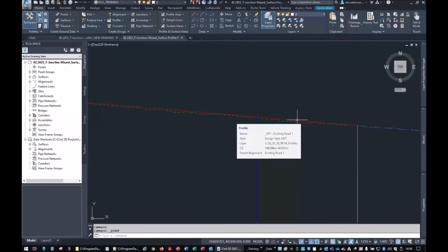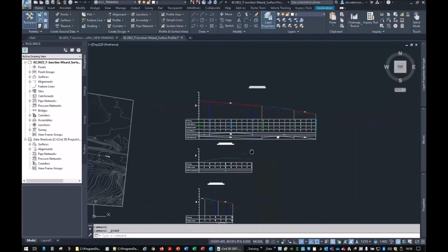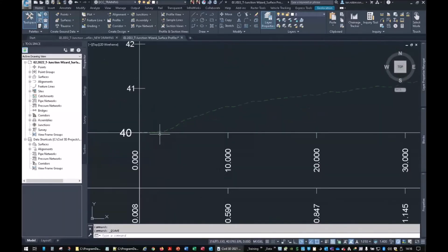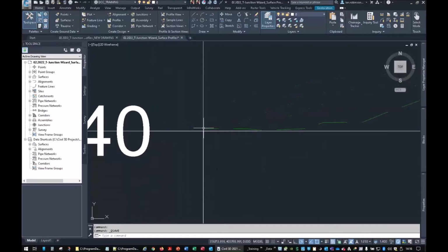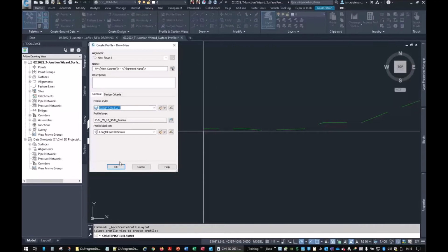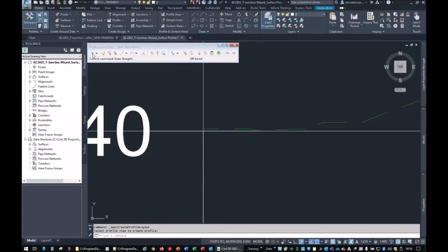And in fact, if you see me doing it manually, I'll put a road on it first, put a surface on it, gives me a tie-in point. What the wizard will do very nicely is tie in for you. So all you need to do is just be very rough. Just get it close to where you want it to be. So it's around the 40s, this kind of starting point. So I'll just draw my profile around there, not giving two hoots as to the actual level.